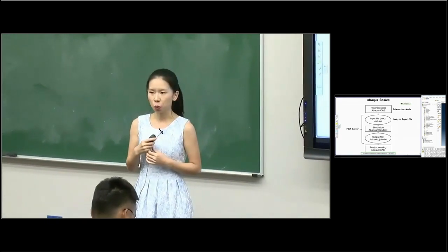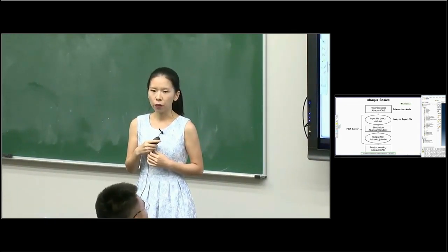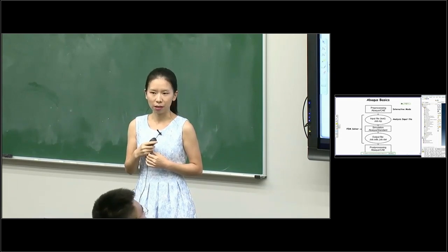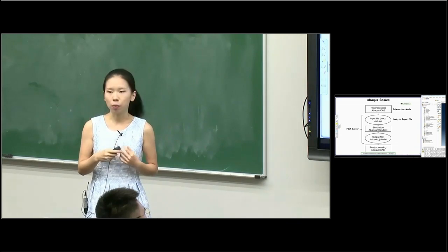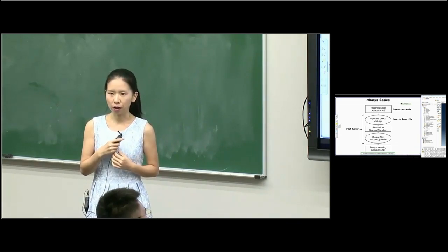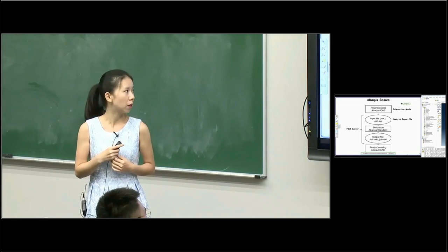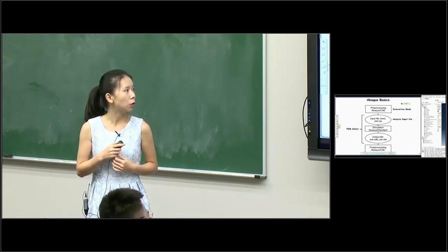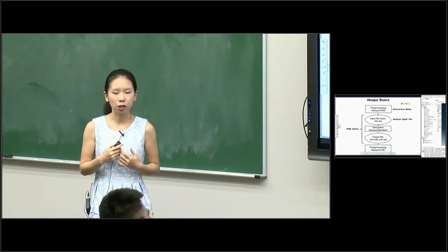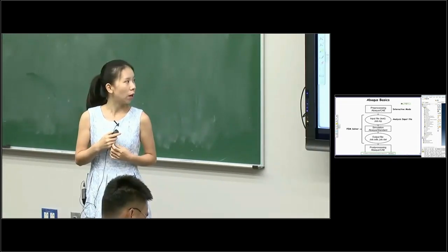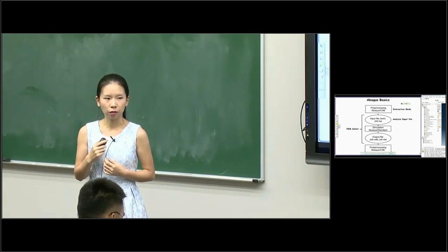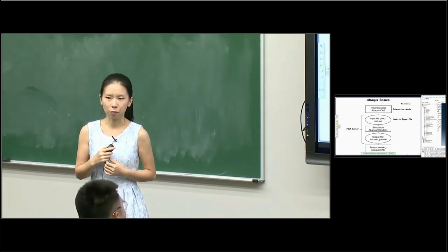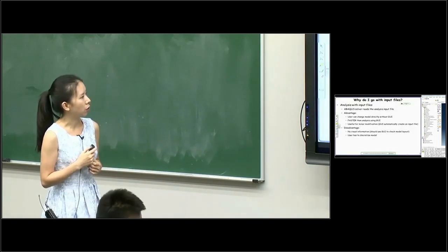But that is just for a simple question. If we need to do something like optimization, it's much faster and easier to modify the parameters in the input file rather than using the graphic user interface. So today I will give some basic information about the input file and how to modify it. I will also use a fully stressed design as an example to do a demonstration on ABAQUS.